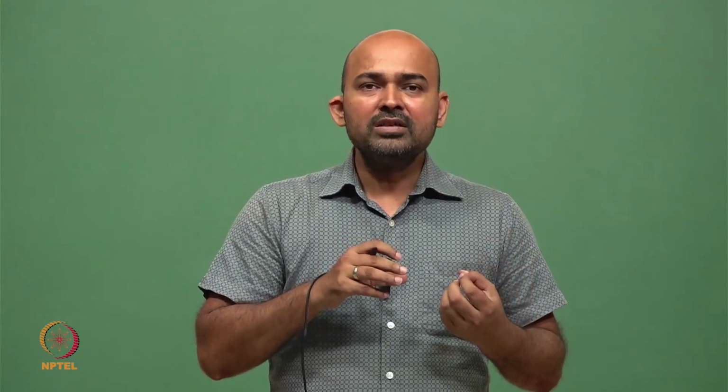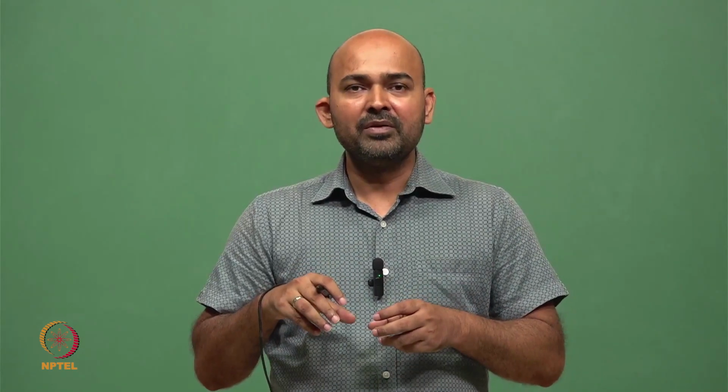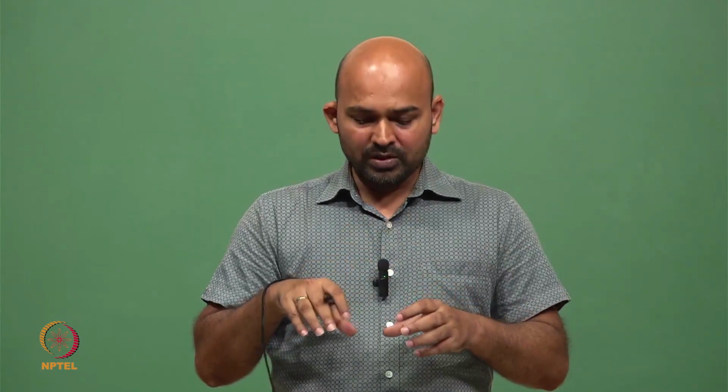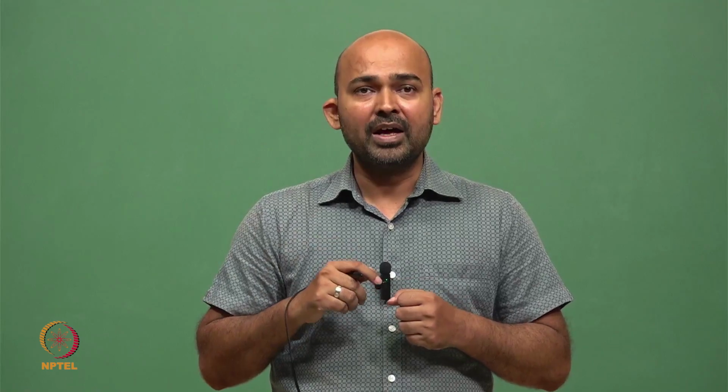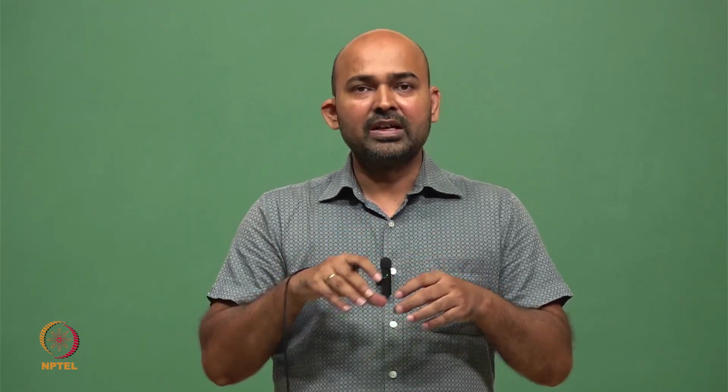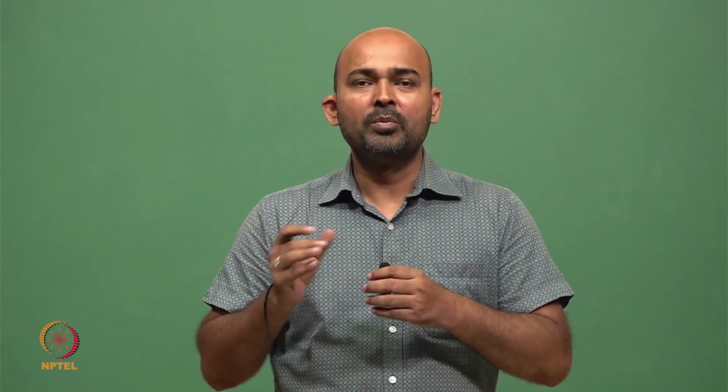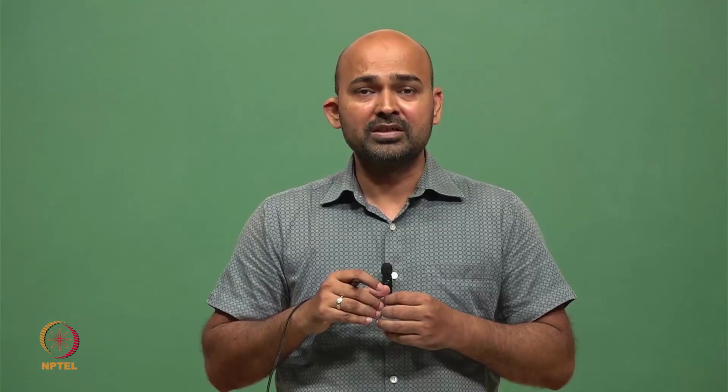This noise also gets amplified by the linear amplifier, because the amplifier cannot differentiate between signal and noise. Whatever is the input to the linear amplifier is going to be amplified. So the signal is amplified, but the noise also gets amplified. Most of the time this linear amplifier is also followed by some filter, which can be a low pass filter, depending upon the application.